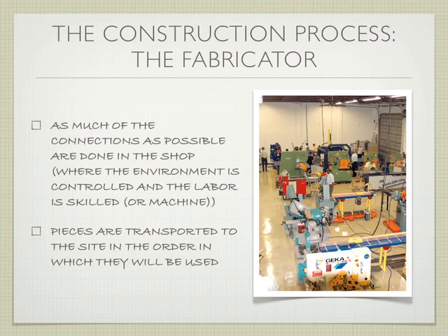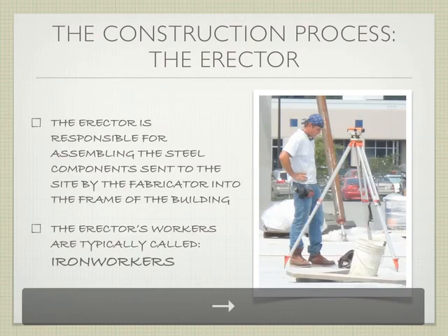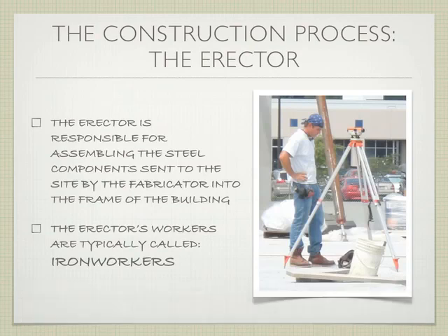That's the point of going off on one of these sidebar tangent stories: to emphasize how important it is to do as much of the welding as possible not on the site. The pieces are then going to be transported to the site, hopefully in the order that they would be used. It doesn't do any good to make the topmost beam first and ship that to the site and have it sitting there waiting. So they're going to start at the bottom and work their way up. Each shipment that comes to the site should be the next realm of steel that's going to go into the particular building.